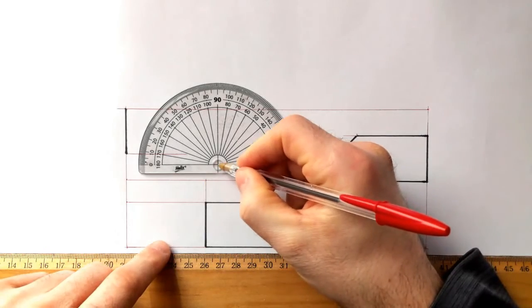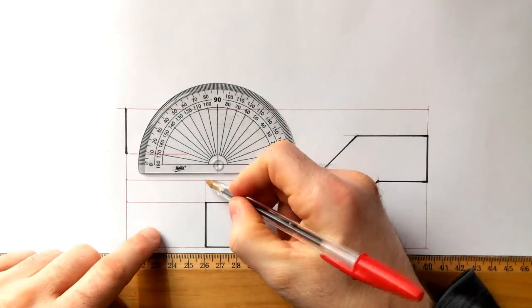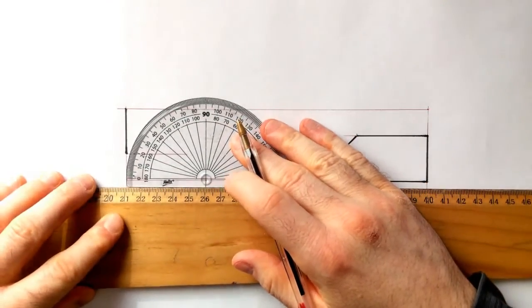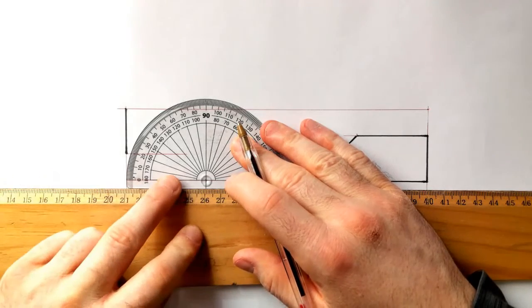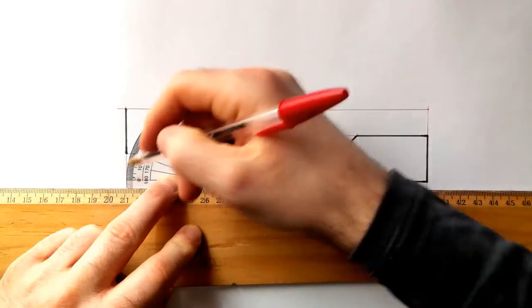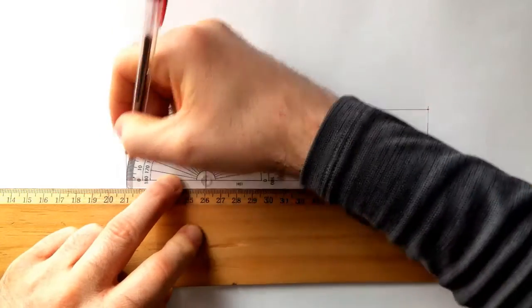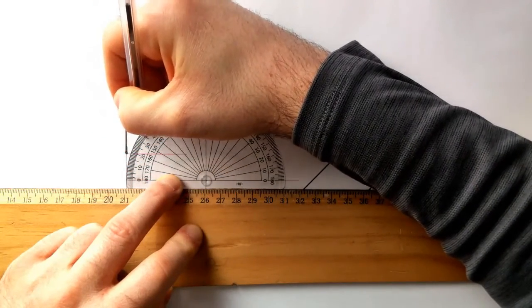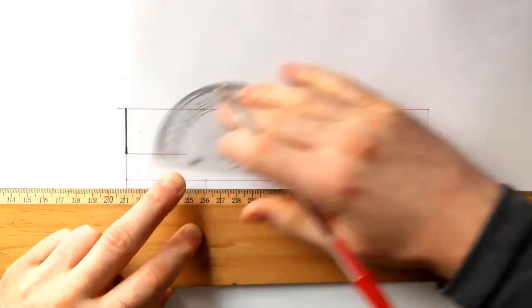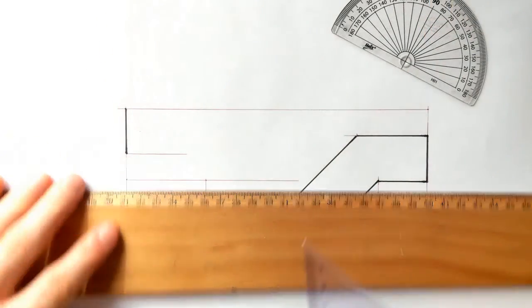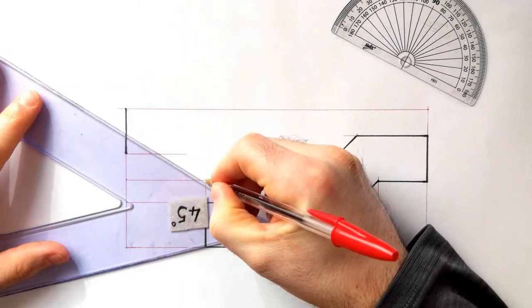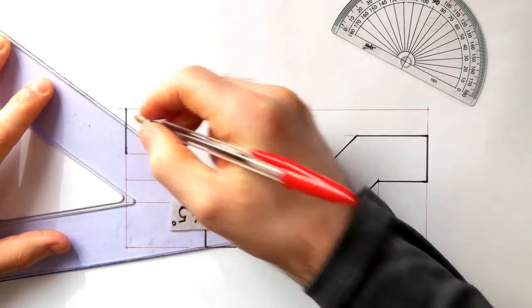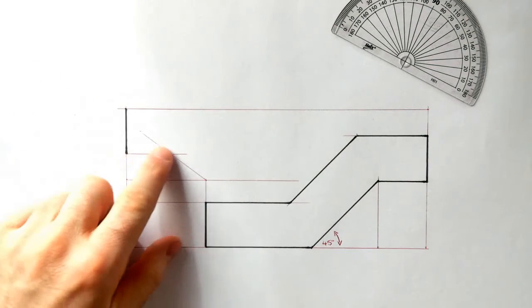So with the zero of the protractor, the middle of the protractor, popped onto this point right here, and I'm going to use my T-square because it is on a horizontal line, and it helps me then zero in my edge. I'm going to project up from that point at 36 degrees reading this way. So 30 is here, 35, 36. I have my little mark there, okay, might be hard to see in the screen. But at 36, there we have it projected up, and there we have that portion that we're going to need in a minute.